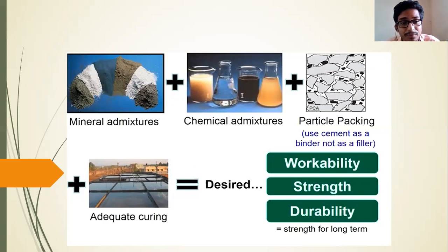Nowadays we have different types of mineral admixtures. We'll see these things a couple of slides later, to increase the density or to use as a filler. But the more reactive materials you use in the concrete system, the more distress may happen due to chemical reactions. So usage of more cement is not always a good idea. Don't believe the myth that if more cement, more strength will come. If more admixture, then more strength will come.